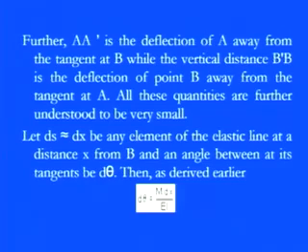All these quantities are understood to be very, very small, because if they are very large, then it goes beyond that limit, and we have a permanent set of deflections, and then these theories are not at all applicable. So just keep this in your mind: whatever deflections come in these beams, particularly under these loadings, they are very, very small, and they are just up to the limit of the elastic region, so that whenever you remove the load, it comes back to its original state.